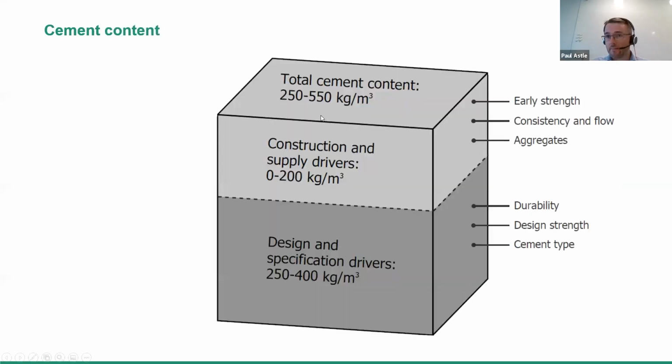So that was cement type, but then we've got to think about cement content. And this is a real winner actually, because just bringing down the cement content is just a saving. That's what we want to focus on. We haven't got to come up with any new material, we just bring down the content.